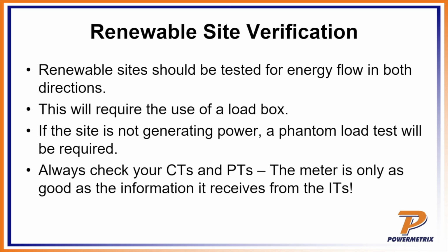Another useful part of a load box is that if the site's not generating power, you can go and plug in directly and add phantom load to that system, thereby being able to test the system much quicker. Our 335 product is a very good example of that. It has a 5 amp load box, which is programmable for both either delivered or received energy.